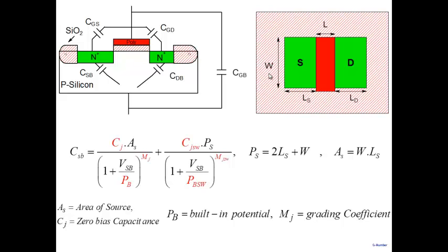So when you do design of a MOSFET, after the design is complete, what you end up getting is an L value and a W value. Nowhere will you see in the expressions for current that LS enters into the expression. Where LS enters is in the capacitance here. So when you draw a schematic and do a design, you'll get W and L, you don't get LS.